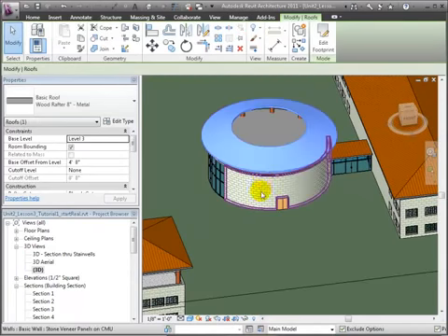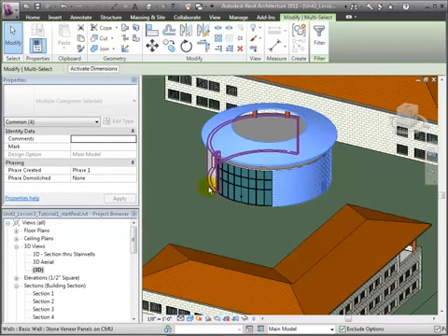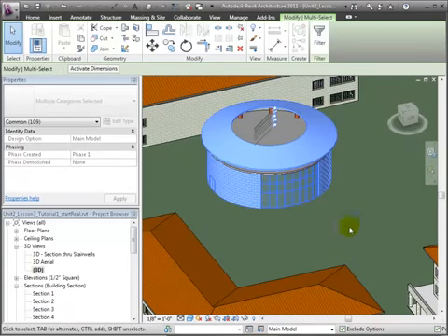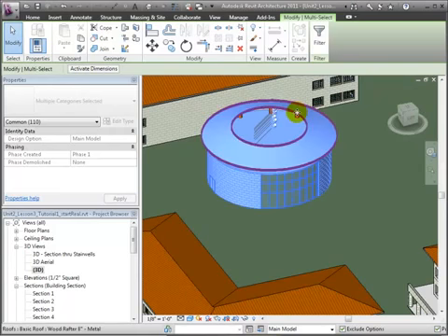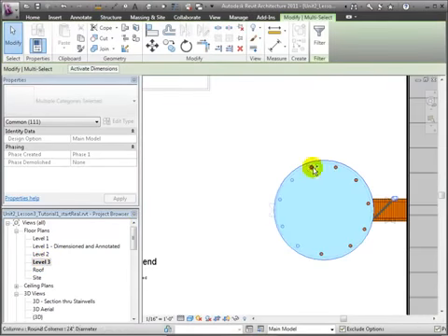Next, we select all the components that belong to the option set and click Add to Sets, designating the set and options in the dialog. We'll select to only put it in option 1 of the set.